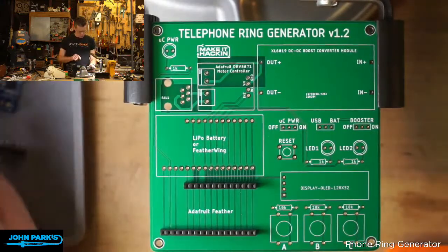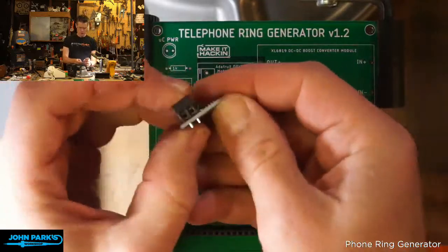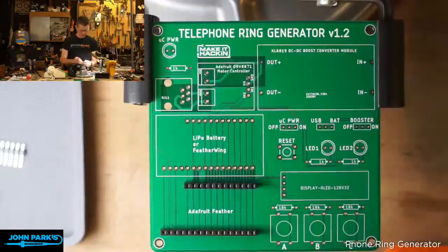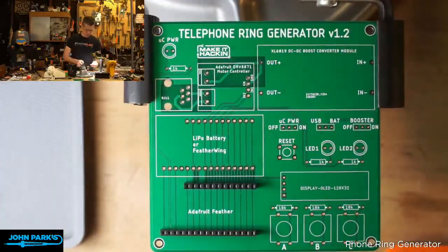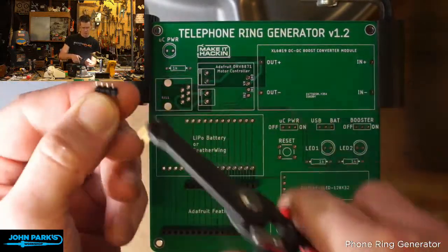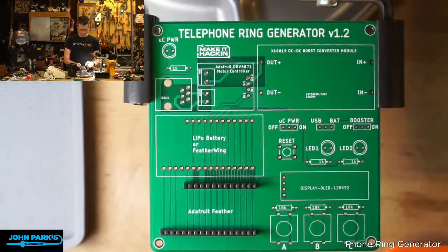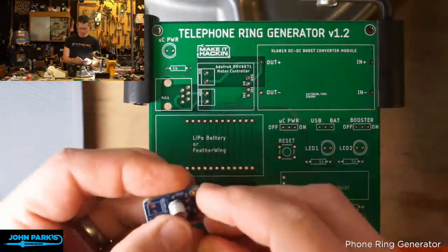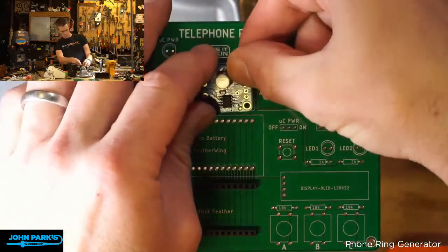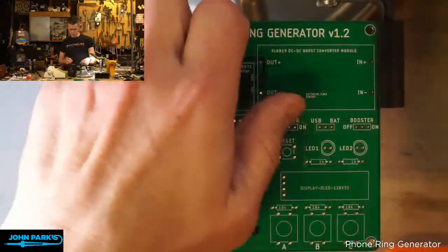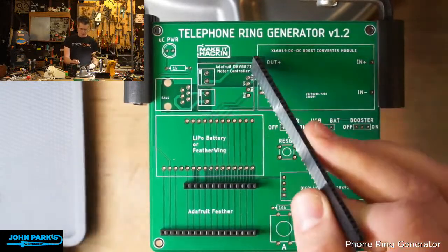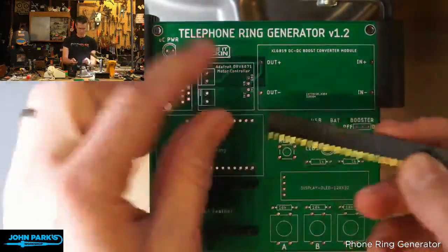But let's see. Okay, so the first thing with the motor controller is to connect the terminal blocks and the header pins to that. So we'll start with these header pins. There are 4 of them, and it came with a little strip of 6, so I'm just going to snap off those, and that can go in like that. Again, you could use a strip of headers to connect that to the board non-permanently. It keeps everything agile.